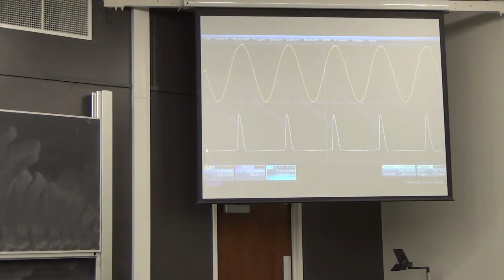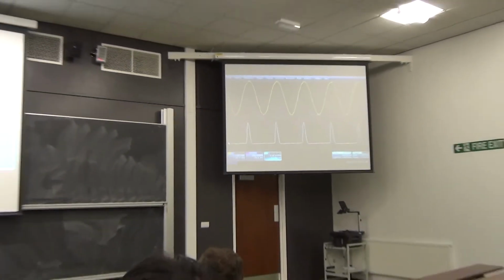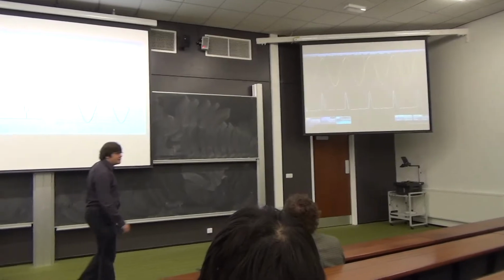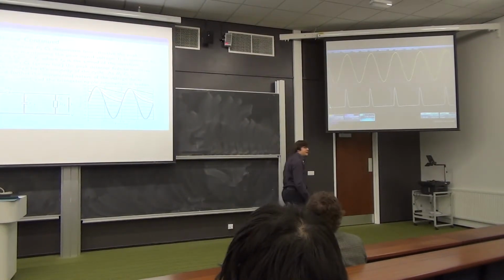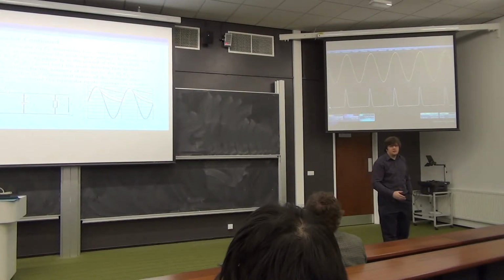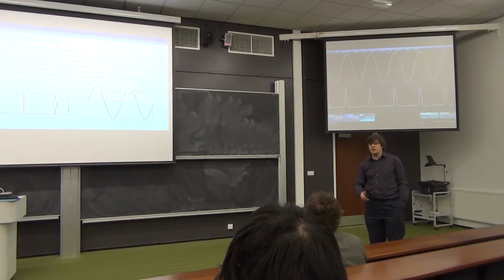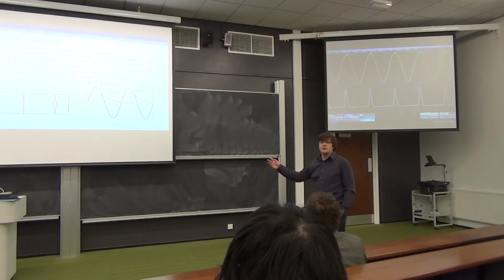So my next question will be, what happens if we change the value of R? What would we expect to see? What happens to these lines? I keep C constant and I'll change R. My time constant will change. Let's assume I make it 100 ohms. It's a kilo ohm at the moment, by the way.